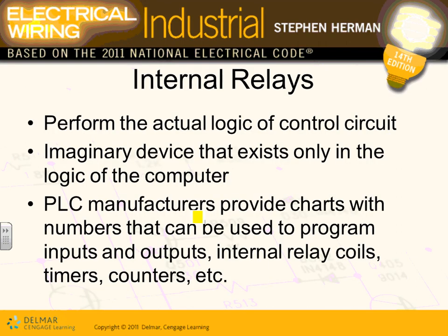Then we have internal relays, guys. The nice thing about a PLC is that instead of building relays, like if you don't have a PLC, every time you have to close and open a contact, you have to have a relay. Relays and timers and counters can be virtual devices inside the PLCs. Isn't that what Scott told you guys when you walked into his lab? He said the beauty of a PLC is you can create, for the most part, as many relays, counters, and timers as you want.